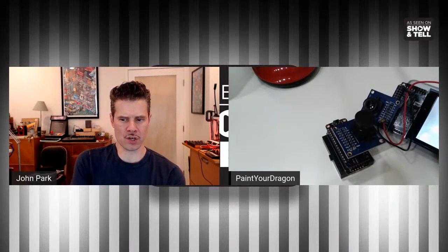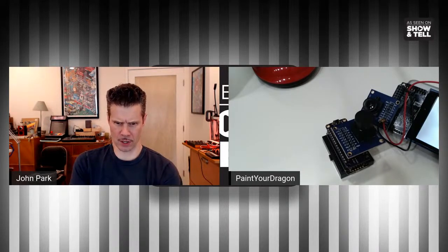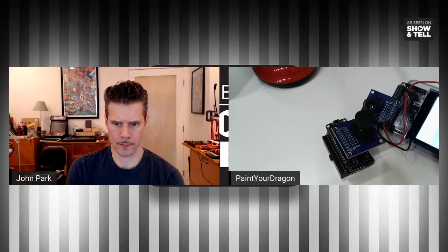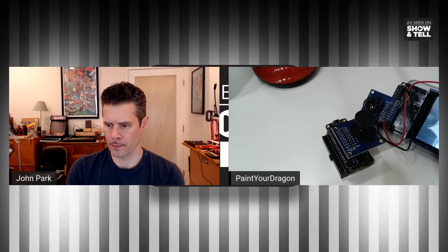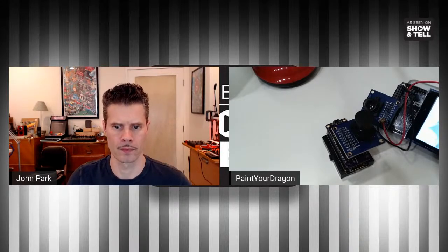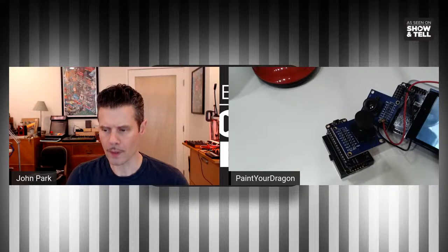That's terrific. And remind me, what is the camera interface that you're using? Peripheral capture controller, which outputs 8 bits in parallel. Here's the link to the guide. It's not like a common thing like SPI. It's something very specific that the SAMD21 doesn't have this peripheral, but the 51 does have it. That's how we're able to get this live feed off the camera.